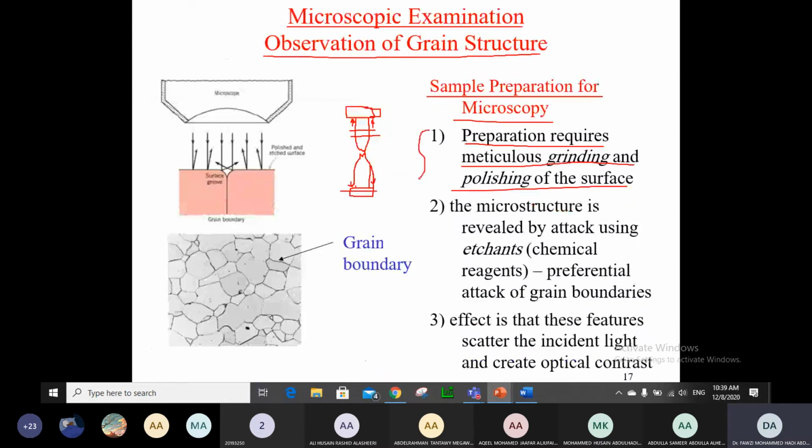First, in these processes that we do in stage 1, the grinding and the polishing, what we do is that we try to get a very straight surface of the microstructure. At the beginning, it was having a lot of this and that. We try to cut that and grind that and then polish it in order to have only the difference between the ups and downs of maximum, as we have seen, 1 micron.